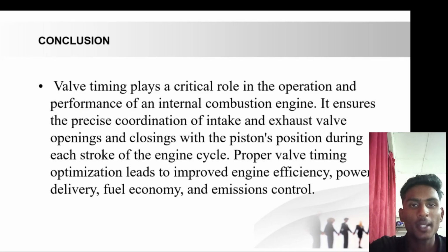Conclusion. Valve timing plays a critical role in the operation and performance of internal combustion engines. It ensures the precise coordination of intake and exhaust valve opening and closing with the piston position during each stroke of the engine cycle. Proper valve timing optimization leads to improved engine efficiency, power delivery, fuel economy and emission control.